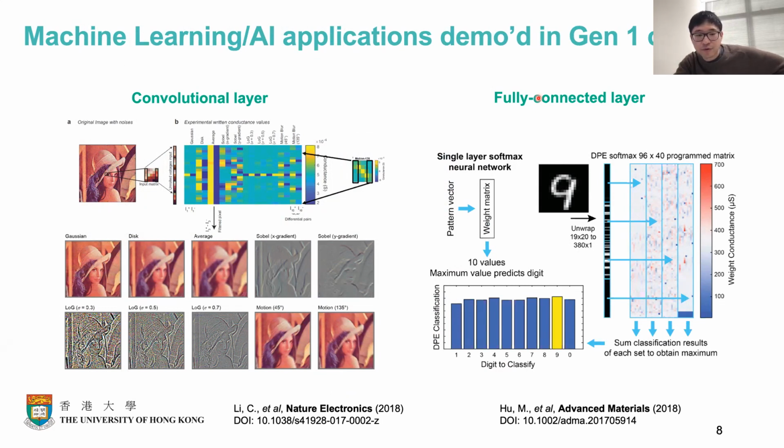But this is for inference, which means we program pre-trained weights. We train the weights in the computer and then transfer the weights into the memristor crossbar with this peripheral. After programming, we are not going to change the device at all. For most scenarios, for example edge computing, we don't have to change those values as long as it's accurate. But I will introduce a little later that this is not an ideal situation, and many more devices can have defects, so we have to come up with some solutions to solve this